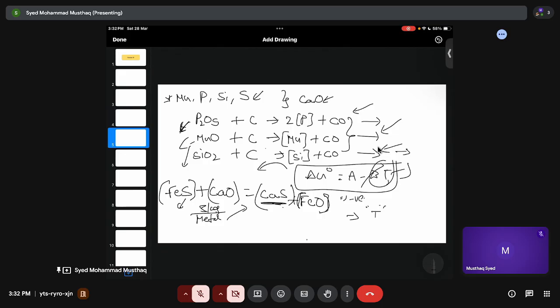And again, as I said before, maybe I said it wrong. Sulfur needs reducing atmospheres, right? Because oxygen and sulfur belong to the same family. They need reducing atmospheres, and because you have reducing atmospheres here, with carbon monoxide, this sulfur can be easily removed here. So it's better to remove it from this blast furnace instead of in your steel making. Okay? And after this, you will have the steel making process, right? So this is what we see in the blast furnace.